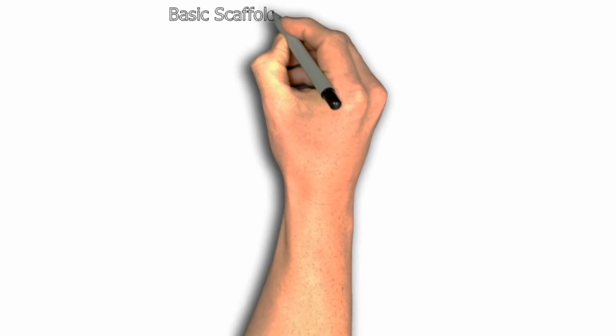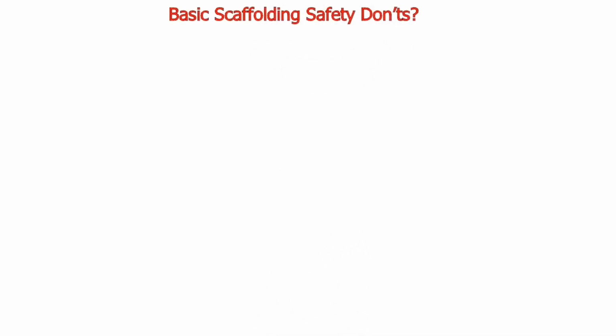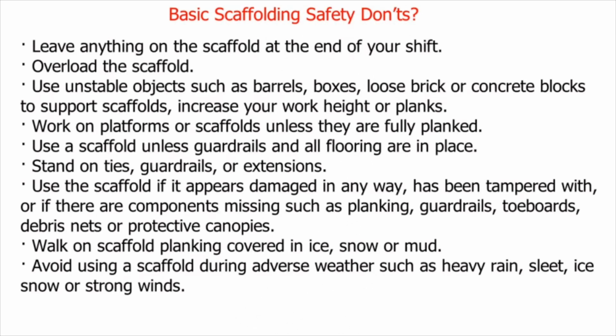Basic scaffolding safety don'ts. Leave anything on the scaffold at the end of your shift. Overload the scaffold. Use unstable objects such as barrels, boxes, loose brick or concrete blocks to support scaffolds. Increase your work height or planks.